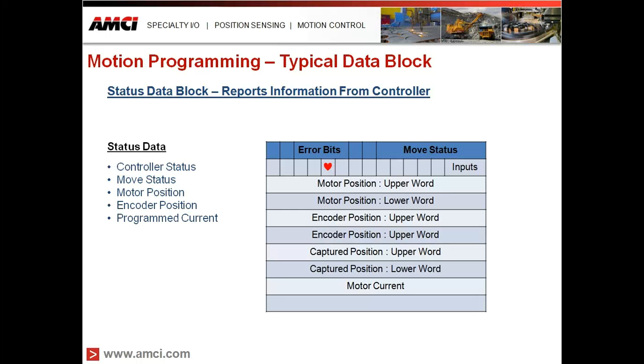Okay, I have a question here, and it's about the data structure of the position and what is upperword and lowerword. In all of our devices, whether we're talking about these Ethernet IP devices or even our PLC modules, we break up the large values, which could be the motor position, velocity commands, numbers that are greater than, say, 32,000, into 2 words because we're looking at a 16-bit data word when we're transferring it over. So for those larger than 32,000, we came up with this method of sending over data. And that method is breaking it up into what we call upperword and lowerword.